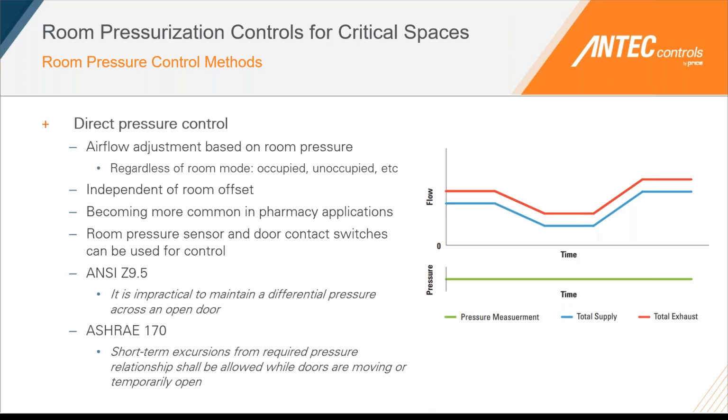For these applications with direct pressure control, it is really important that you have a pressure sensor to give us the feedback on what that room pressure reading is, and then additionally having door contact switches. So if that door is left open, we're not trying to control the room pressure with the massive hole that is the door being left open.